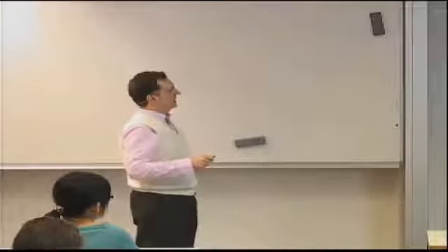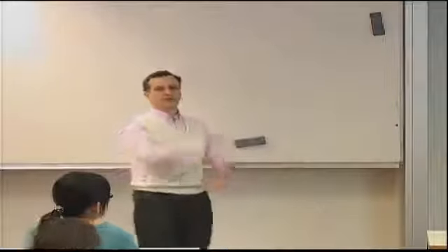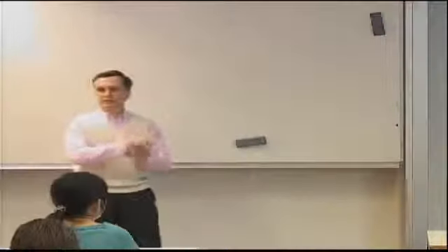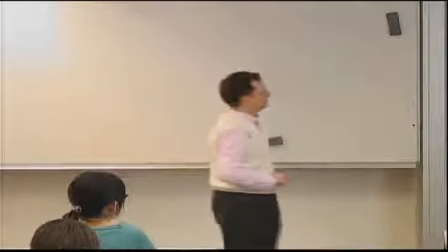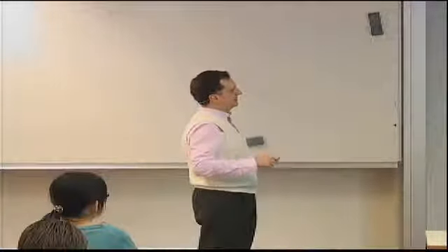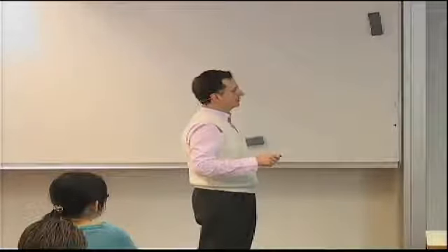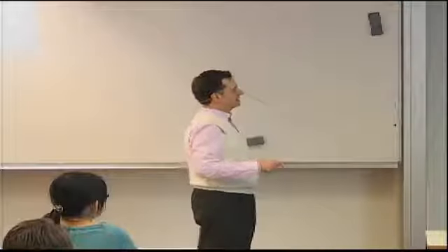So just all the properties that might be of interest: the A matrix for each of the 2 layups, layup A, layup B. Notice the A matrix is identical because reshuffling a symmetric laminate does not change your A matrix. But it does change significantly your D matrix, which you can see by comparing the 2 columns here for D11 and so on. Thickness is the same.